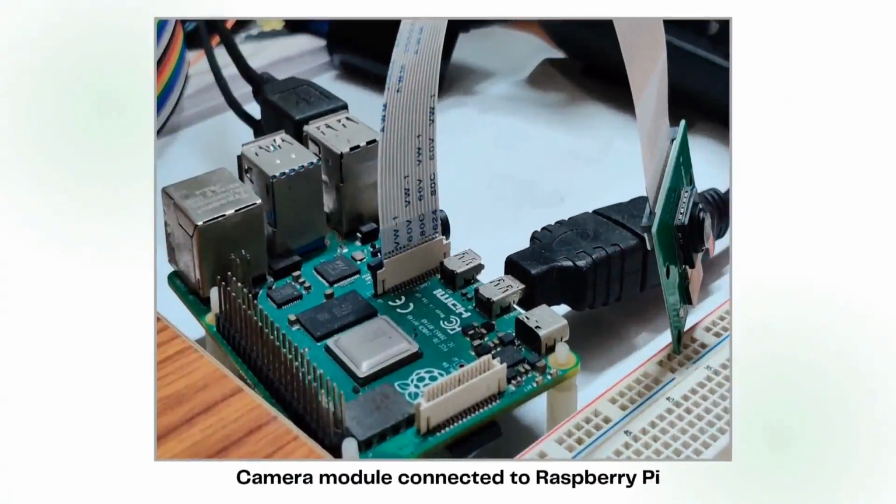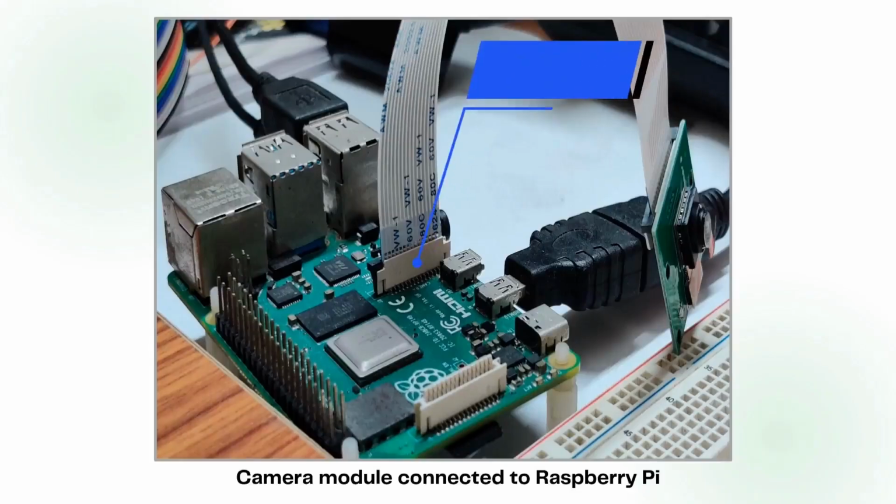Connect and configure. Connecting the module. To connect the sensor PCB to the SBC, first locate the camera module CSI connector on the PCB. Lift the plastic clip to loosen the connector. Then insert the ribbon cable into the connector. Make sure the contacts on the ribbon cable are facing the contacts inside the connector. After that, tighten the clip by pushing it.